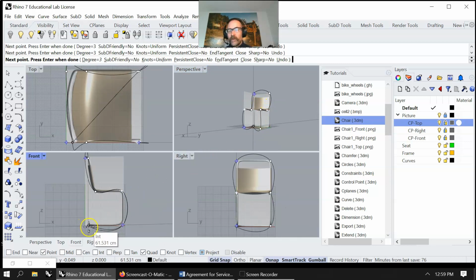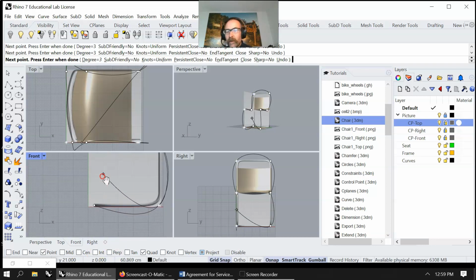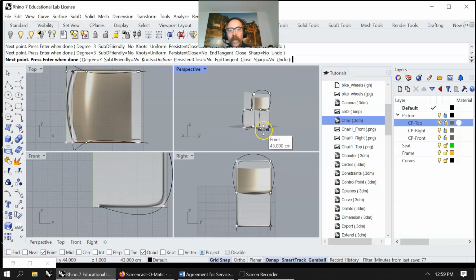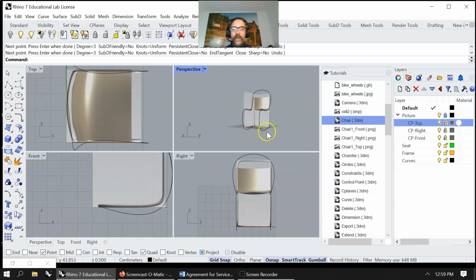We want our last point to be here. And I think we'll leave this one open. Because I don't want to close it and have some trouble, I'm going to reference that point. Hopefully I got onto the right point referenced. That one I don't want to snap to the grid. I'm going to target, control, click, set elevator mode, and then go to our last point here, and we'll end it off. And we're going to just hit enter to end.